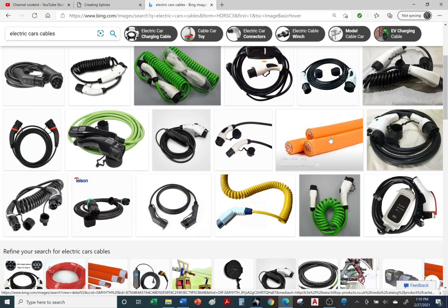So when you model this in 3D, in CATIA or another software, you can limit how much you can bend it by applying a radius. Like, hey, we don't want to bend it less than, let's say, 10 millimeter radius. I'm just making up numbers. If you try and create a tight turn with the small radius, it'll break.